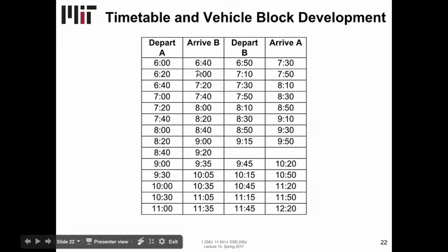We tie the trips in the first direction with trips in the reverse direction. The first trip departs at 6 and arrives at 6:40. Considering a 10 minute layover, we schedule the first trip for the reverse direction at 6:50, and it is anticipated to arrive at 7:30. This continues for the whole timetable, given the travel times between the two ends and the headways.